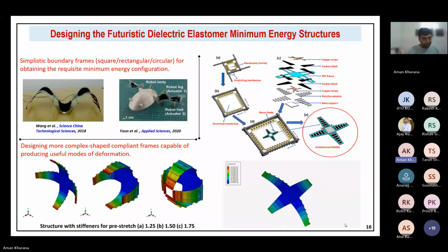So there are two different ways. First, if you see in the market, there are different types of material for dielectric elastomer. One is the acrylic elastomer that has a strong viscoelastic behavior. That is the VHP membrane that we were using initially. And there is also a silicone elastomer, which is also a dielectric membrane. That silicone elastomer will not have this viscoelastic behavior. That is one thing.